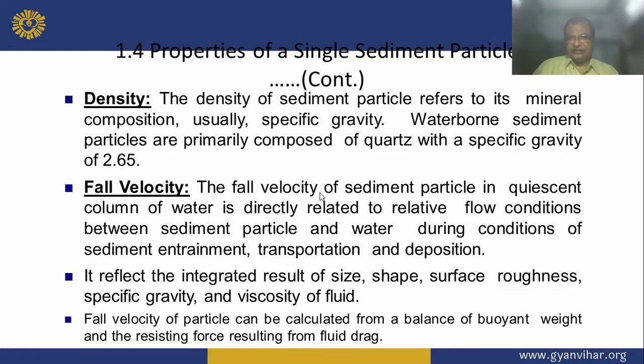The density of a sediment particle refers to its mineral composition, usually specific gravity. Water-borne sediment particles are normally composed of quartz with a specific gravity of 2.65.